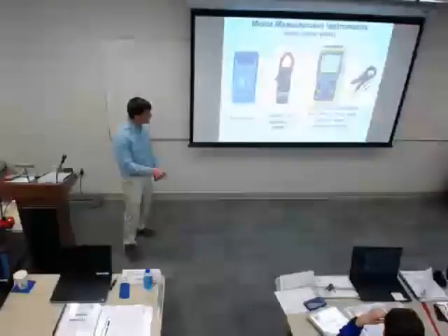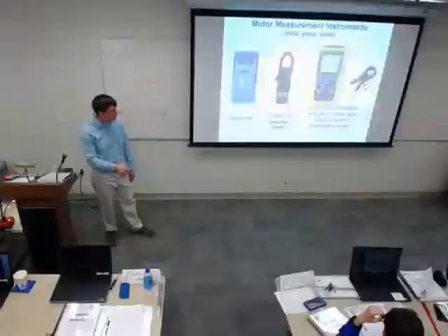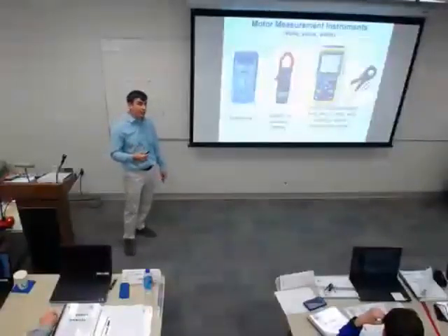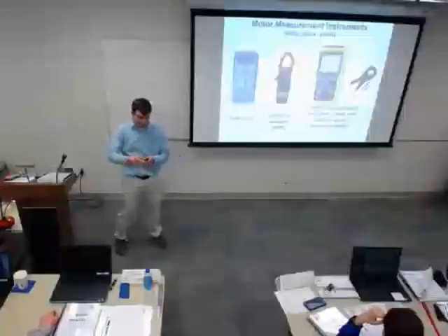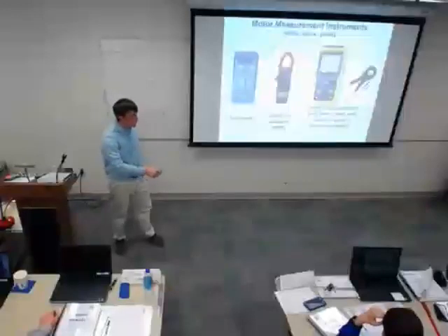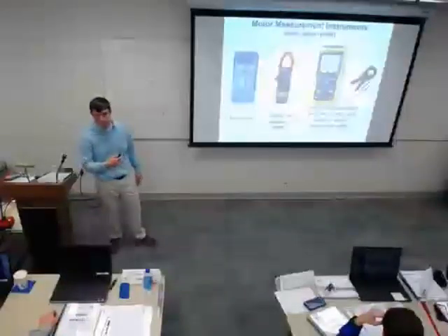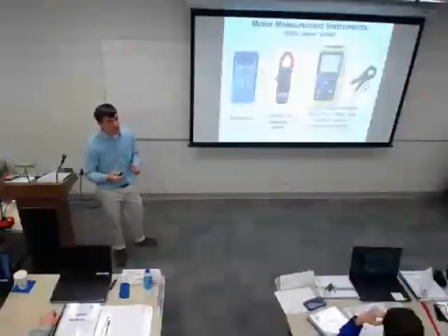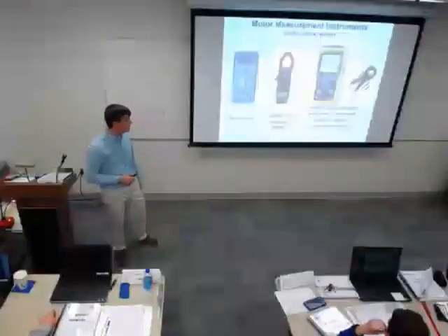You'll see this meter being an RMS, root mean square. You definitely want to see that the meter they're using is a root mean square meter, because otherwise it's just doing some calculation to give you your current as if it were a sine wave, and a root mean square takes that into consideration when it gives you a number. You should never have a TAB guy show up with a cheaper meter. I'm not sure how it determines it, but it's not right. This is what the TAB standard requires.